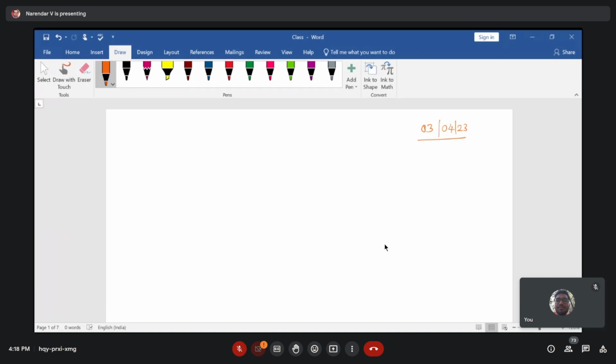And we had also seen what are the different second order effects that a MOSFET can face during the operation of your analog circuits. And there are three different types of second order effects that we had seen. The first one is subthreshold conduction. The second one is your body biasing effect. Third one is channel length modulation.